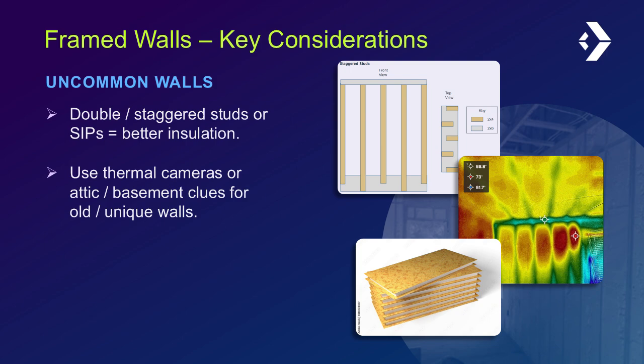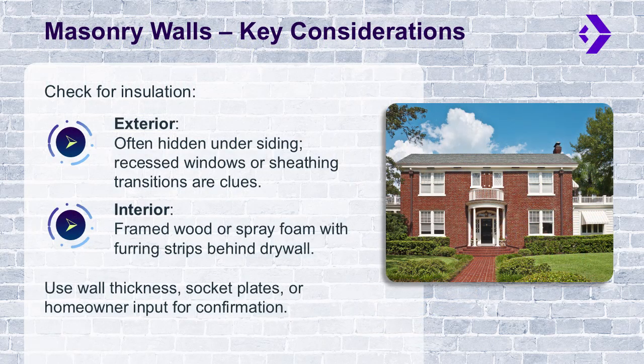If you see walls that are more than 7 inches thick, put a little more time into trying to figure out what's between the sheathing and the drywall. Similar guidance applies to extremely old walls, with either lath and plaster interiors or brick facades.